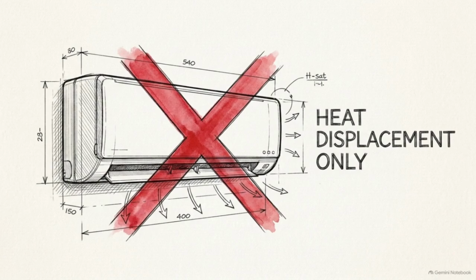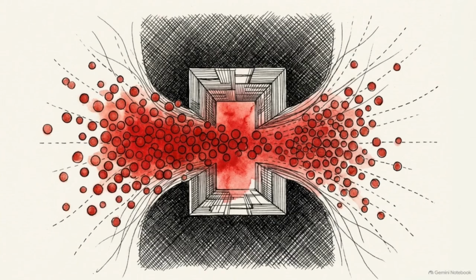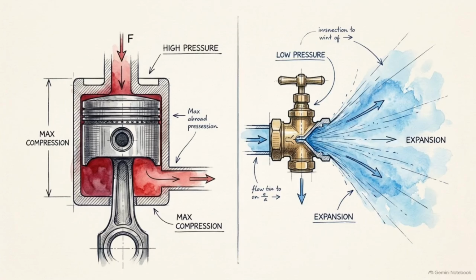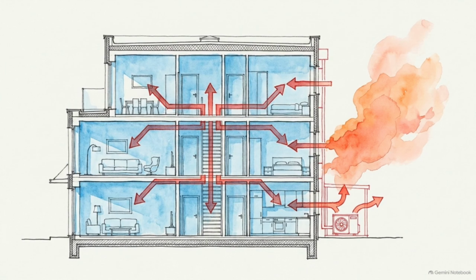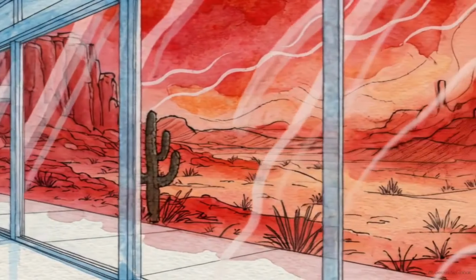This brings us back to the opening reality. An air conditioning unit does not generate cold. It relies on passive heat exchange points. The evaporator acts as the indoor doorway for heat to enter, and the condenser acts as the outdoor doorway for heat to exit. These doorways are operated by active mechanical engines. The compressor and the expansion device apply the pressure changes required to push the heat along its path. The vapor compression cycle provides the physical proof. Refrigeration is the engineered displacement of heat. Mastering this specific thermodynamic loop is what allows us to stabilize indoor environments, regardless of the temperature outside.